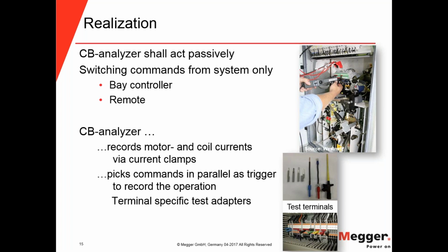So the analyzer just works passively. It just records the current signals, and it starts with an external trigger pulse, for instance when the closing and opening commands are sent from the control room.